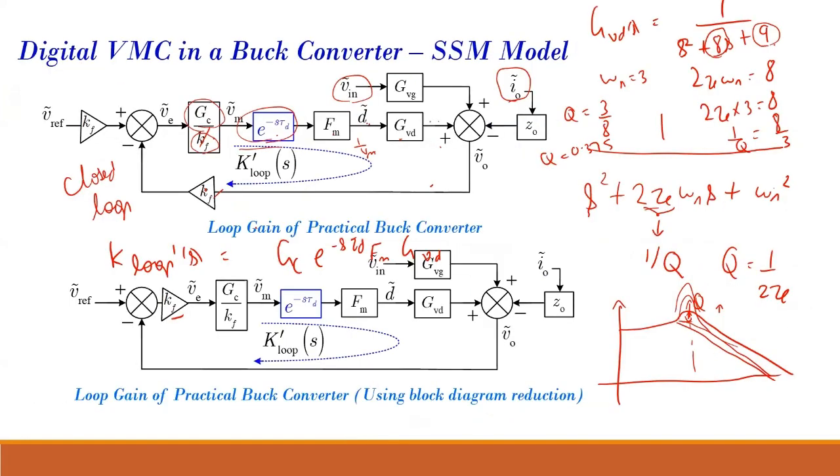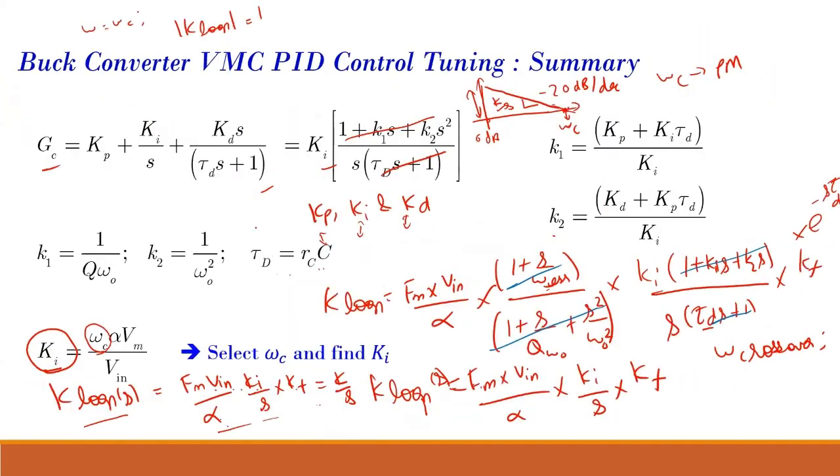Okay, let us see. This is the tau d. So it is like a low pass filter. This tau d s plus 1 acts like a low pass filter. This also will be present in your op-amp. In your op-amp, it will have a limit. It cannot accept frequencies of very high range. There will be a certain frequency from which it starts attenuating the output. So that is effectively modeled as tau d s plus 1.